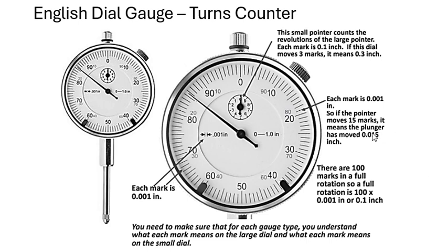The plunger, I call it the contact, some people call it the plunger. It's just a stem with your contact right here, because as you know, we're trying to measure height. So this going up and down is very important, and it's very sensitive. Every time the contact touches the surface of the object you're measuring, you're going to see the dial pointer going around, either dropping on this side or on this side. This we call the negative side, and that we call the positive side.